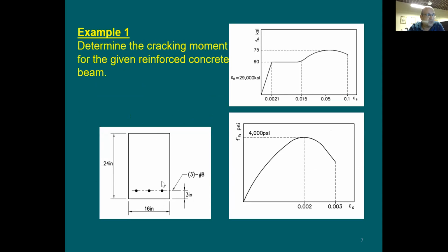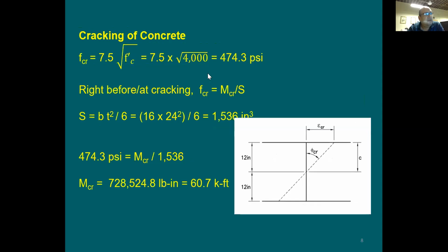Now, once the concrete starts to crack, the concrete is not going to be working with you, and the rebar is going to start to take some good tension force. Okay? This is the simplest way of handling a problem like this.